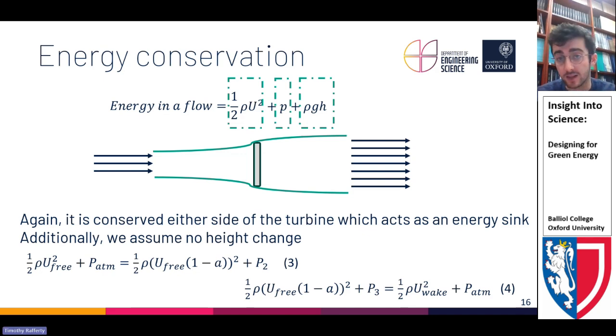Yeah, it's the kinetic energy of the flow. We're having to use density here again because we're looking at a mass flow rate. I'll give you the second one. This is called the static energy. It's the static pressure, but you can think of it as almost like an energy. And can anyone tell me what the third one is? I kind of expect you to know this one as well. Yeah, gravitational energy, the idea of lifting something up high and you have a height change.